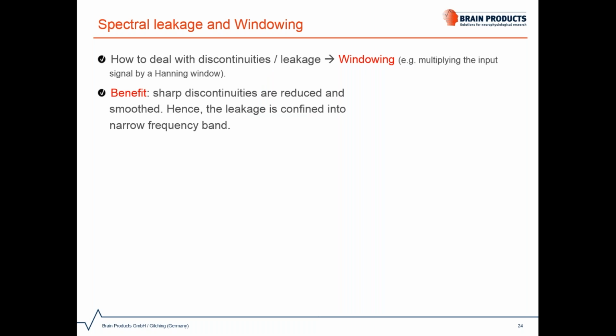When the windowed snippet of the signal is copied and appended, the appended signal will now have a smooth transition and no more abrupt transition. Therefore, the leakage will be reduced and confined to a narrow frequency range, rather than affecting the entire frequency spectrum.